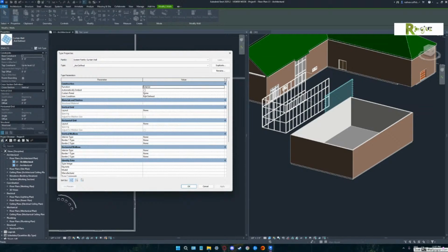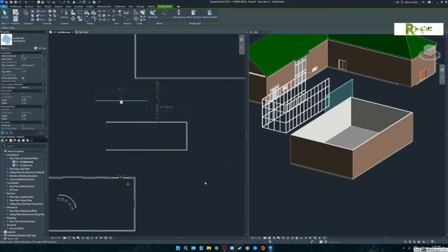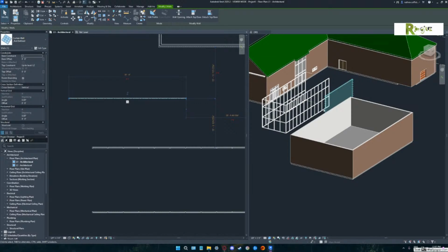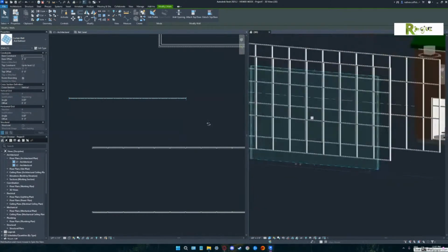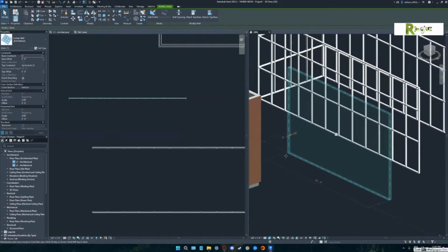So this used to be called curtain wall 1 for 15 years. They call it now not defined. Now I'll show you the neat thing about this curtain wall. So go ahead and hit cancel and zoom into that guy, and maybe in your 3D mode. We're going to need to see this in 3D. How about you orbit me a little bit? There you go. Perfect. Like that.